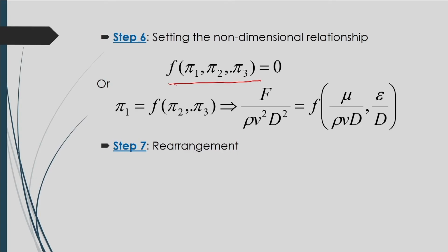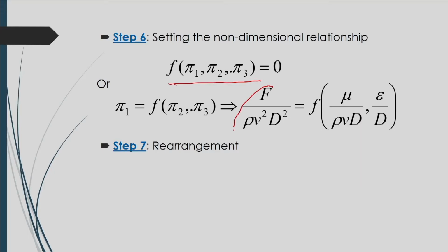So, in that way you can form it, but since in your problem it is seen that flow resistance depends on the other variables, that is, f depends on the other variables, in that case you have to make the functionality like this: the group that comes based on f, you have to make it the dependent dimensionless group, and this will be made in terms of the other dimensionless groups.